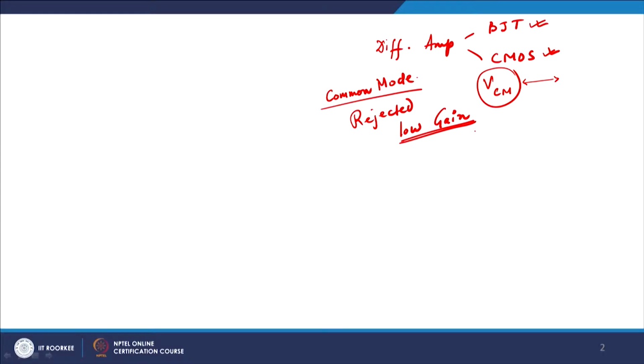We also saw that common mode signals, and that is one of the major concerns, which is basically noise, for example common mode signals to both the arms of your BJT, get rejected. All your common mode signals have got very low gain, and as a result they get rejected very easily, which means that if you feed a noise to both the arms of a symmetrically designed differential amplifier, the noise will be easily rejected.